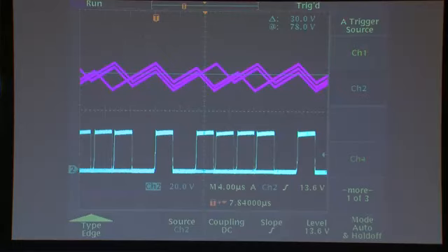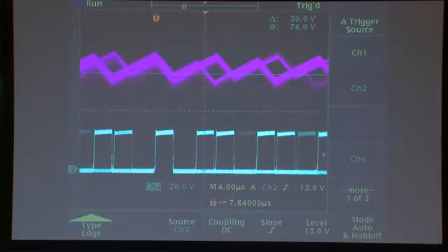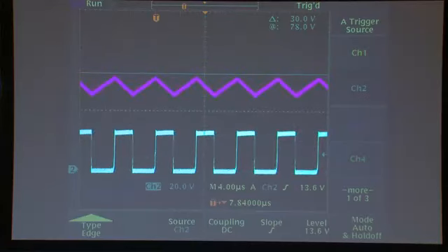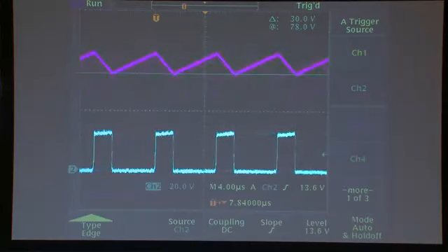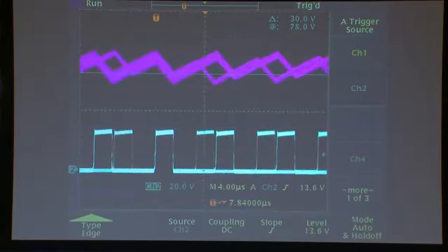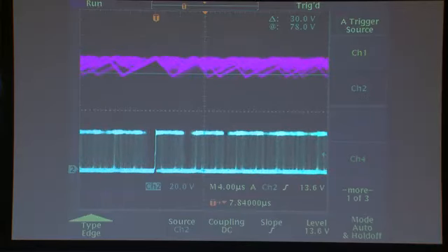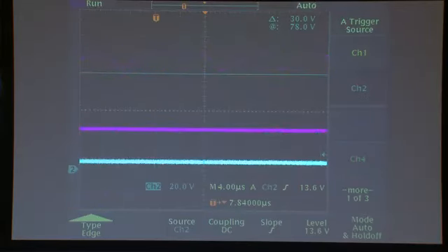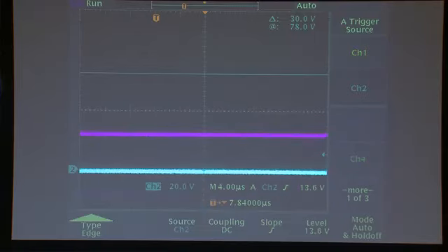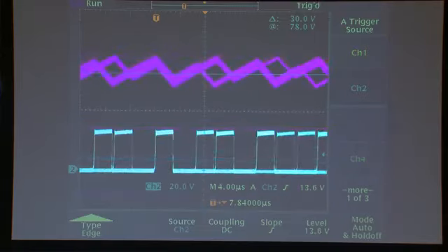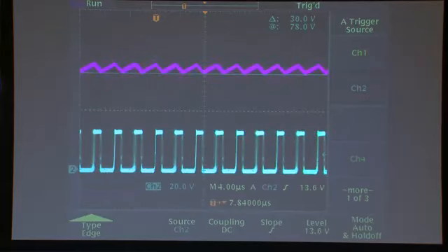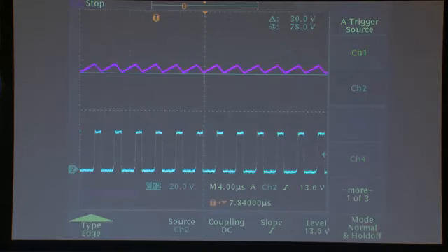And I should say that this is a function of the voltage. If I have a low boosting ratio, it goes away even without a compensating ramp. But the higher I go, because of that ripple instability, I get some really funky behavior. If I throw in my compensating ramp, there, I get nice steady state operation. Okay?